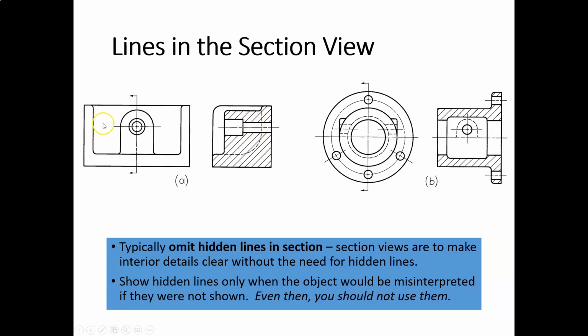And so you really need another view here. You might want to make another section view cutting through that to show this curvature here. That's a difficult thing. I would still avoid doing that because you're not going to be able to dimension it, so you have to figure out how you're going to dimension it. So again, this is probably not a good example.